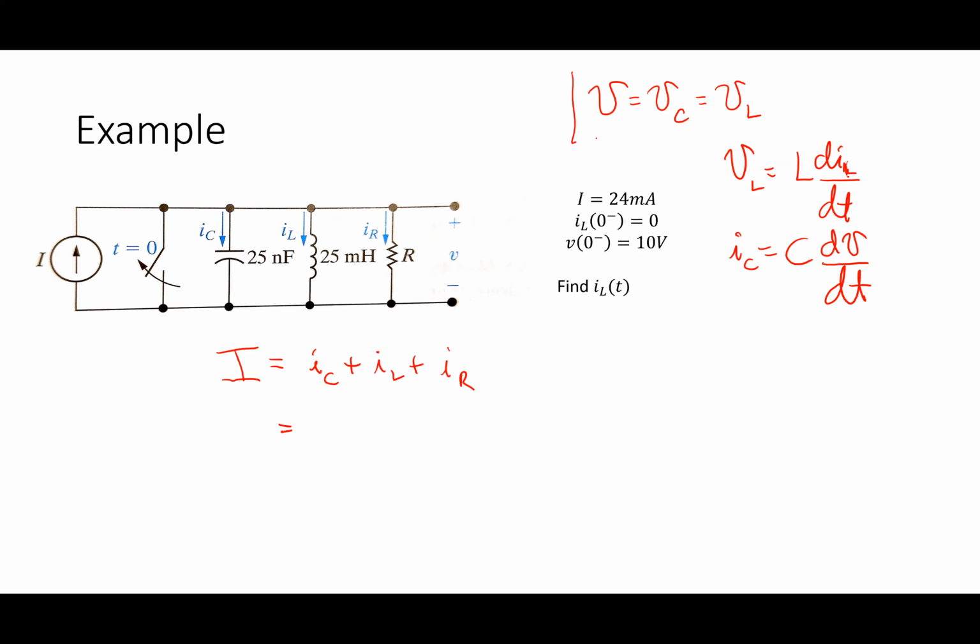Let me give you a hint. Let's use this guy. Let's think about how we could use that I sub R right there. I sub R is what? Help me with Ohm's law on that. V over R, right? We've labeled this as V. Now, how can I get that in terms of inductor current? L over R times dIL/dt. Yeah, L over R, dIL by dt.